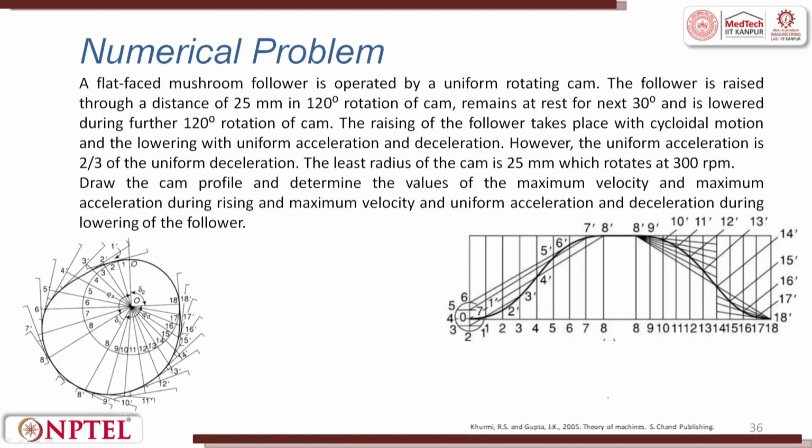The third problem is: the flat face mushroom follower is operated by a uniformly rotating cam. The follower is raised through a distance, the stroke is given, 180 degrees, 120 degrees is given, and the rest is also given. So, after the rest, it rotates 120 degrees. The raising of the follower takes place with a cycloidal motion, and the lowering happens with uniform acceleration and deceleration. However, the uniform acceleration is 2/3 of the uniform deceleration.